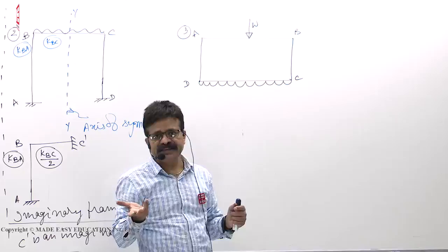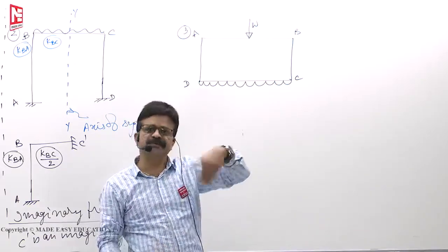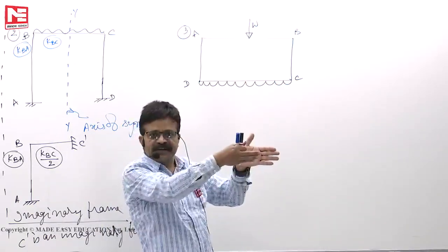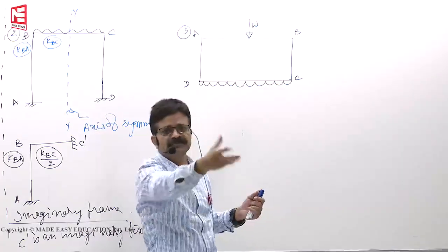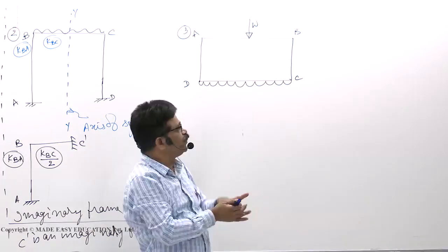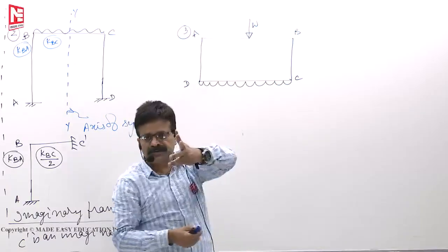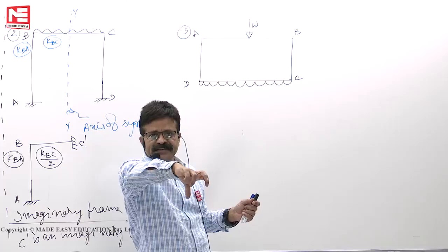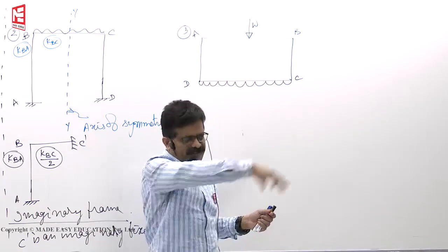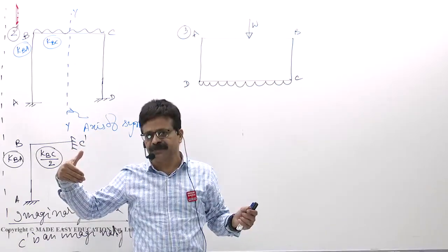Bending of bars are there. So that reinforcing details and all we give it. For 1 meter, whatever reinforcement details you give it, for 1 kilometer length also the same reinforcement you have to repeat. So we analyze generally, like your two-way reinforced slabs are there, say 1 meter width you take and analyze, and whatever reinforcement is there, you extend it and provide it over the full length of the slab.